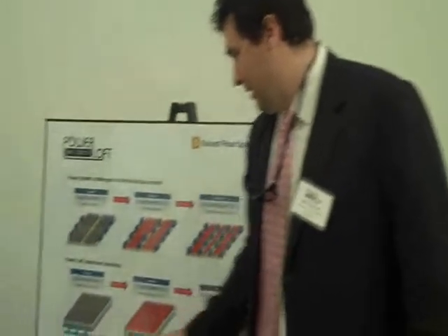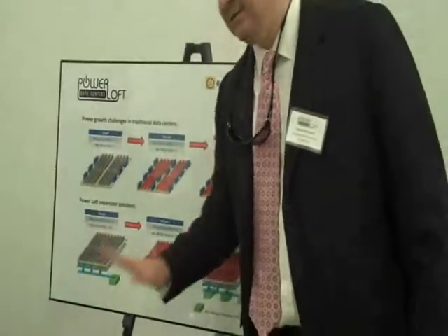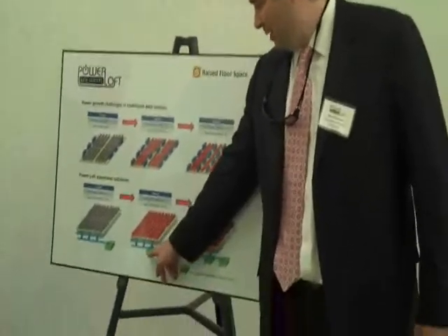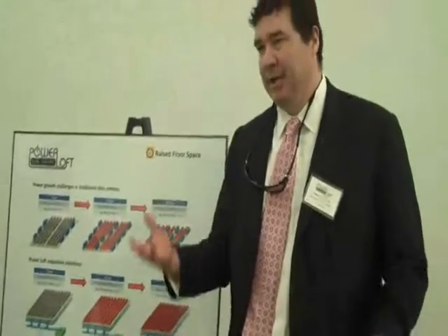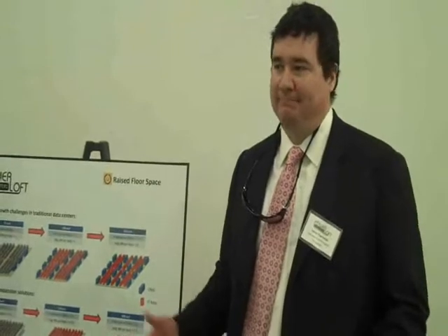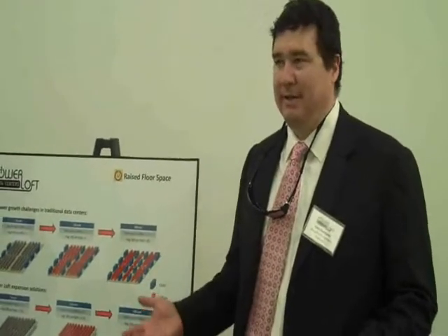In the two-story design, everything happens on the ground level from an HVAC standpoint. So this is your IT load, this is where your servers, your production area is. As you require more power and thus produce more heat, all we do is down below add air handlers, pushing air through. Nothing ever occurs on this raised floor area that is mechanical in nature. So there's no HVAC up here. Everything happens below. So scalable density is a benefit to this design on one hand.